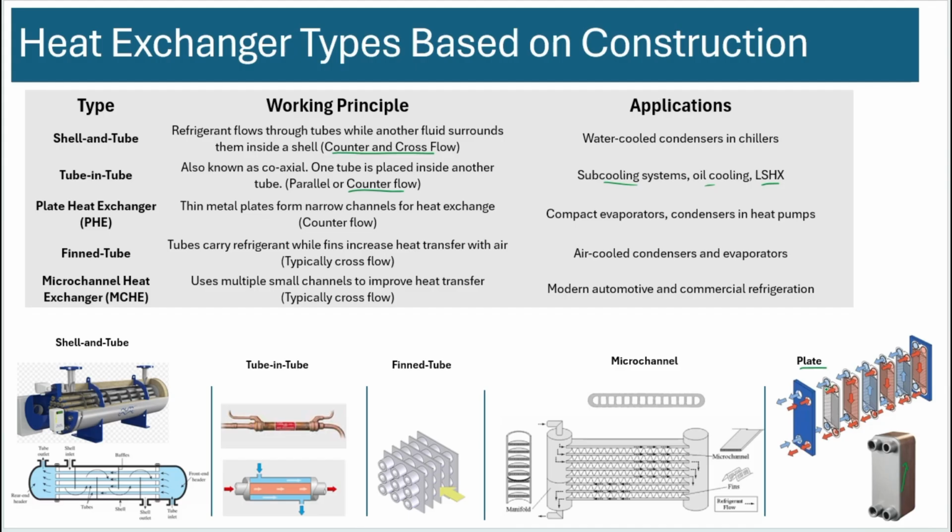So it's designed by carefully arranging these openings between these plates. If you notice, they're always in counterflow configuration. One is going down, the other is going up, always. So it's counterflow, and primarily used for compact evaporators, condensers, etc. It's primarily used for liquid to liquid heat exchange. It's not for liquid to gas.